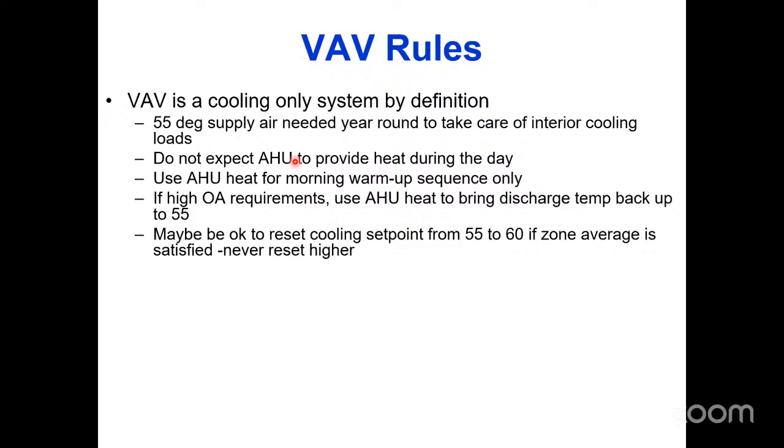And the amount of airflow you need to keep the rooftop gas-fired heater online is pretty high, probably like 80% of the total airflow of the system, which means it forces all your dampers to go open. So the interior zone that wants cooling all day is now going to take 100% heated air in while the other zones get their heat. It's a disaster. Definitely do not try to make that happen.